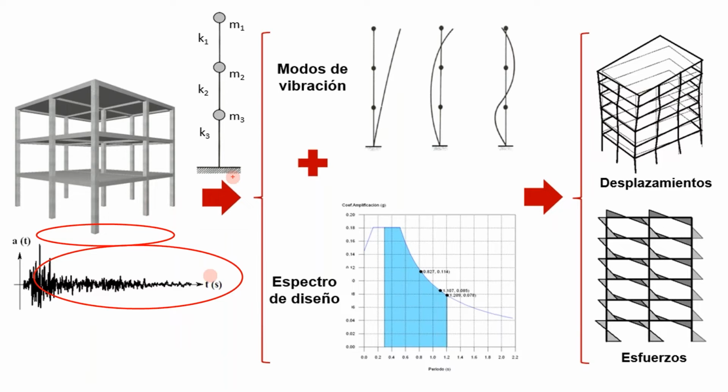And then, using the modal expansion combinations, using the CQC method, we obtain the particular coefficients for different analysis directions, which are the linear response. So by the displacements, we have to correct those displacements according to the code. That drift check is possible because we have in the list a bunch of information regarding that part. So you can check those reports and verify if you are according to the code.